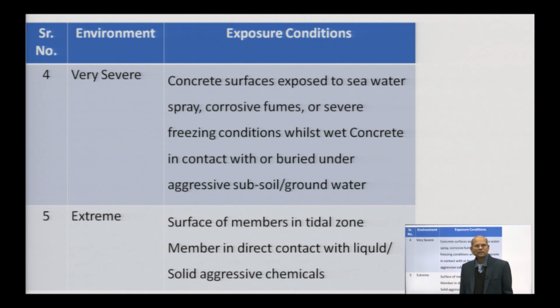Similarly, we have very severe conditions. What is very severe condition? Concrete surfaces exposed to sea water spray, corrosive fumes or severe freezing condition while wet, concrete in contact with or buried under aggressive subsoil or groundwater. So, suppose we are considering an area which is nearer to the coastal area, we have to consider the very severe condition.